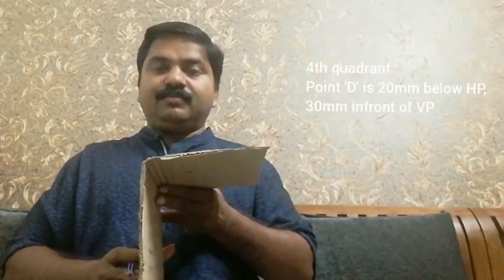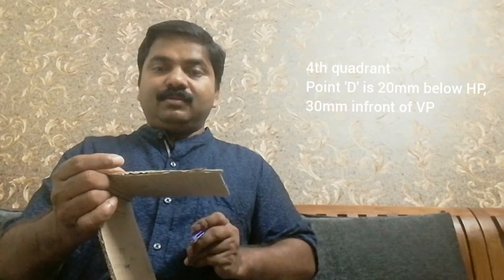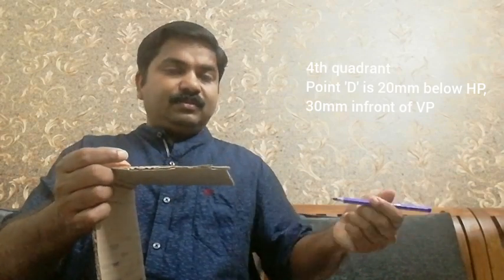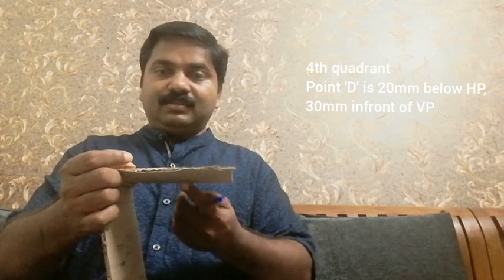This is the fourth quadrant. Now the point is situated here. It is 20 mm below HP and 30 mm in front. The person is looking from this direction, and now the front view will be obtained here, 20 mm below this HP.